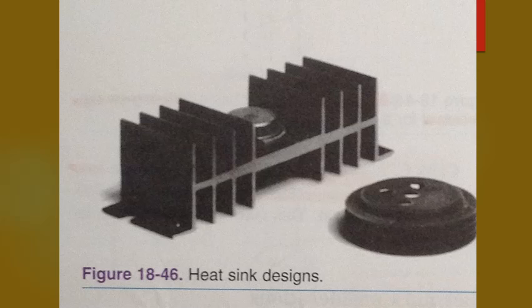Heat will destroy the transistor. When soldering a transistor lead, grasp the lead between the transistor and the connection to be soldered with a pair of long nose pliers. These pliers will act as a heat sink and absorb the heat from the soldering. Use a pencil type soldering iron of no more than 25 watts.